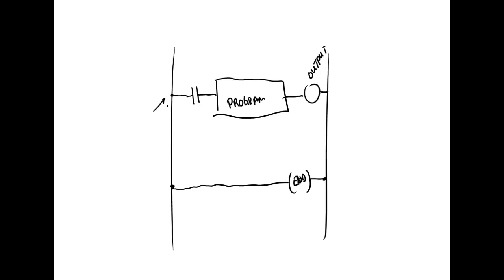User defined, not automatic. For each input or output device instruction, a logic address or simple name is entered above each instruction symbol. This location is predefined by the ladder logic PLC programming application. Note that related to RSLogix 500, once a logical address for a bit instruction is entered at the top of the symbol, the bit address is displayed below the symbol. A block input or output instruction's logical address is entered at a predefined location inside the device symbol.